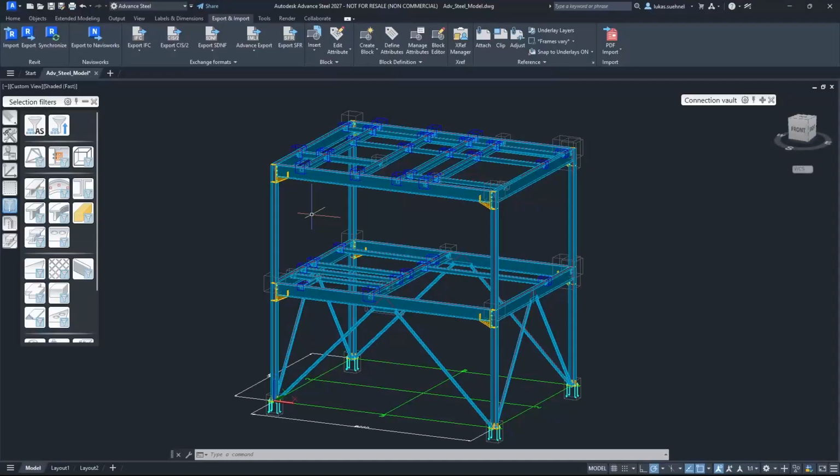There are now multiple ways how you can share this information with the structural engineer. One way would obviously be the IFC format. The Advanced Steel user exports it into IFC, then the structural engineer will import the IFC. He will convert the IFC objects into members, connect them using, for example, the regular rule-based link generator, and then he can design it. That workflow I showed in a previous webinar.